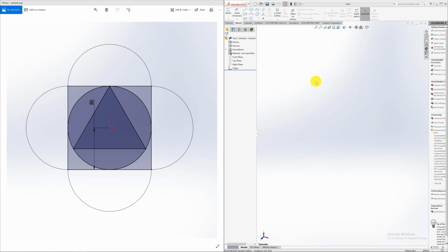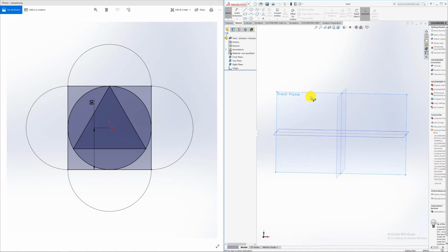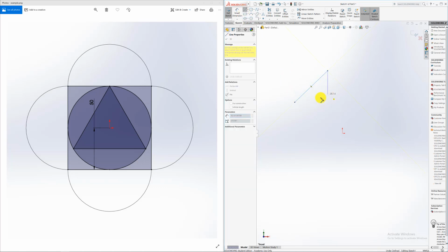If I can draw your attention over to Solidworks, I'm just going to view my plane, and say sketch. I'm just going to sketch something basic, just some lines, to show you what exactly is happening here. So let's say I have two lines, with a placement like this and another one like this. You can actually, with a relation, add that they should be parallel to one another.